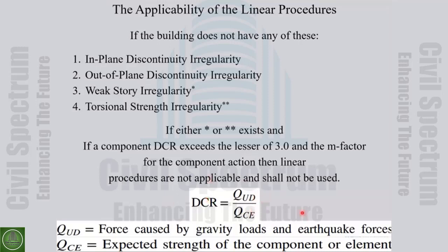Therefore, the easiest way in the linear analysis to know if the building gets damaged or not is to go to the elements and estimate the level of the responses for the different response parameters. For all force control responses, it should be less than one. If it is more than one, the building is collapsed, and the load path, one load path, is failed.